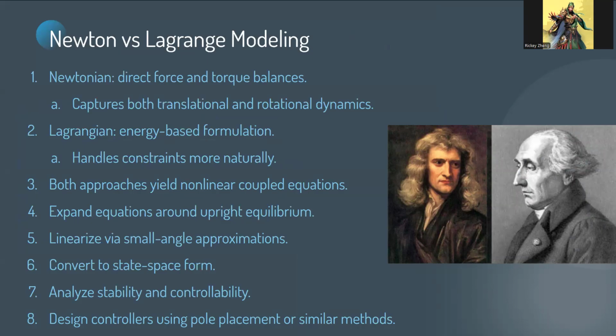The Lagrangian formulation instead relies on energy principles, expressing the dynamics in generalized coordinates and handling constraints more naturally than force-based methods. This makes it especially effective for systems with multiple coupled motions or geometric restrictions. Despite their differences, both approaches produce coupled nonlinear equations of motion.